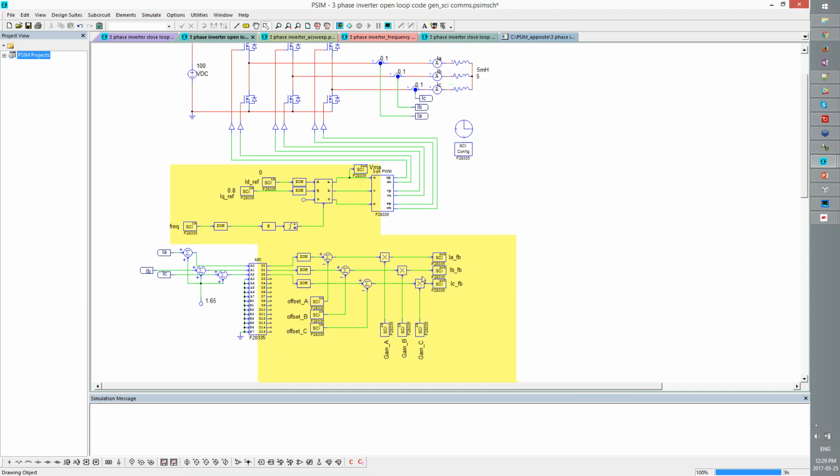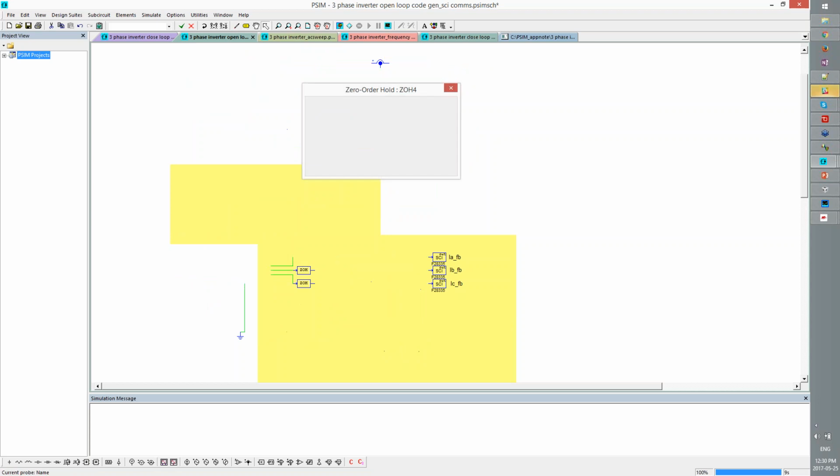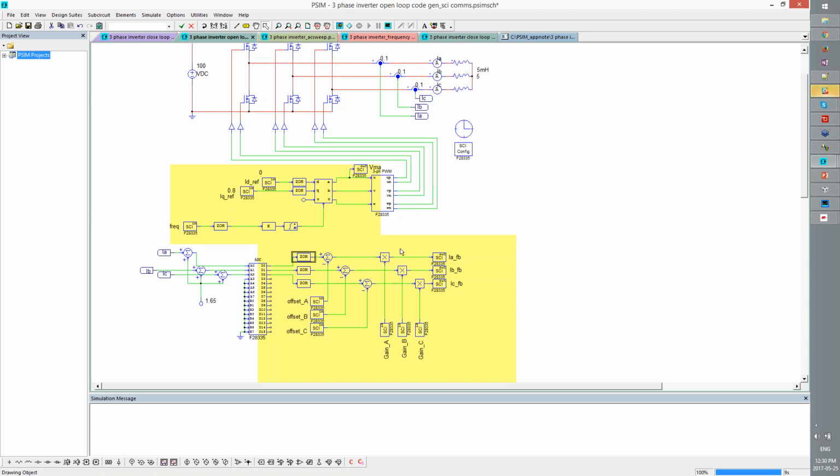You can have a signal defined over here, and that's good, because we can run a simulation of this, like I did earlier. So we can simulate it if there's something there. If there isn't anything there, when you simulate it, it's not going to do anything productive. But when you generate the code, because you've got it wired up here, it's going to do that sampling for you, and the sampling rate defined here is at 10K. So 10K is running.